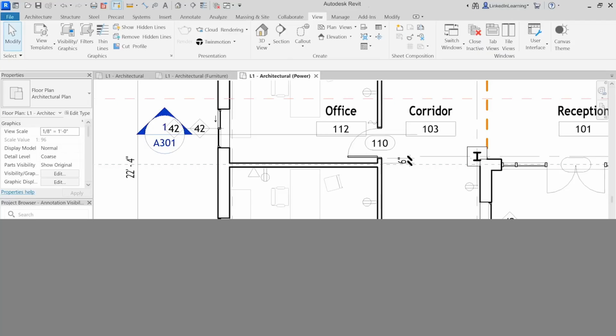Then under patterns, I'm going to click the override button and change the pattern to this diagonal crosshatch small. And then I'll change its color to this medium gray and click OK. So let's click OK and then finally OK one more time. And now you should see that all of the furniture has taken on this crosshatch pattern, and its outline is now bolder than it was before.